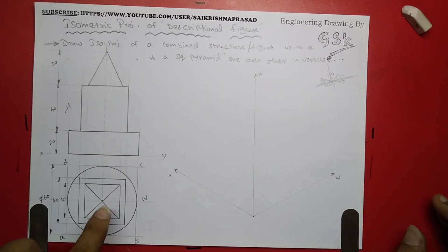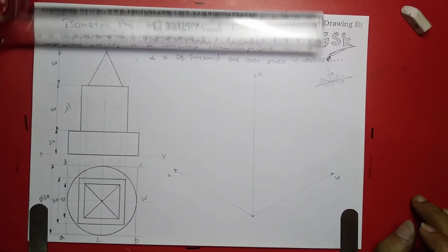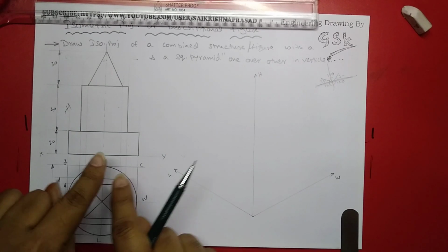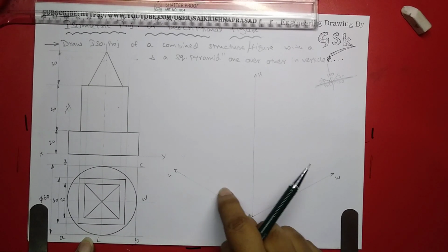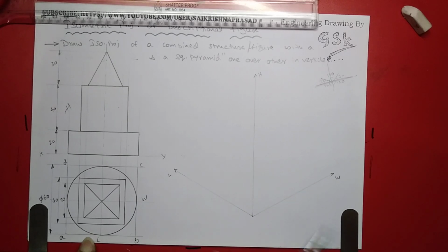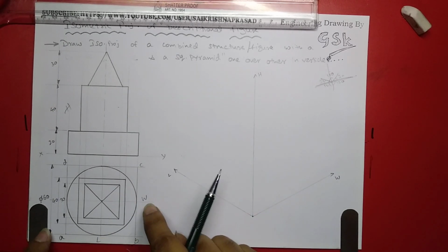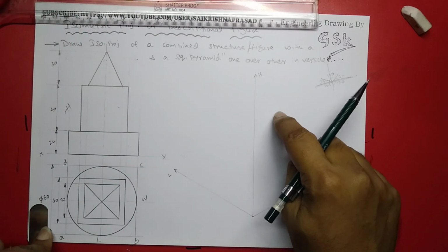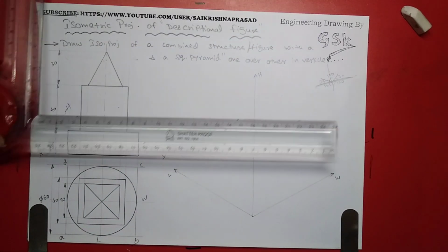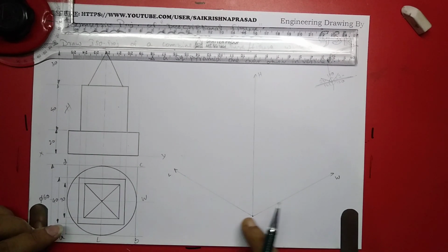So now I have to place this over here. I have already placed the top view in a box, and in the top view we'll be covering length and width. So all the length lines are parallel to this length axis, all the width lines parallel to this width axis, and all the height lines parallel to this height axis. So I'll be placing this box over here.